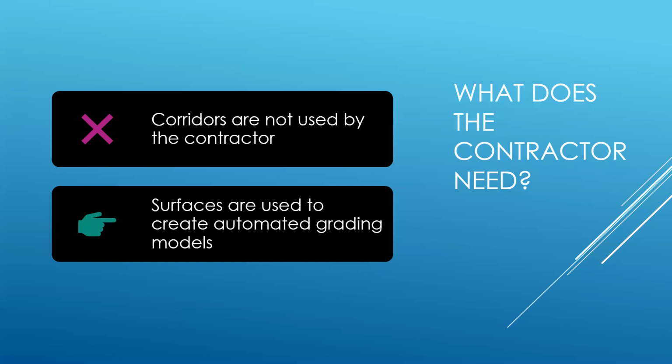So once we completed the Highway 15 project, we wanted to reflect on what we had done. We wanted to question why we use stage models, and we wanted to determine if there was a better way. So first, we questioned the need of stage models due to the issue we found with the lack of flexibility to change. Essentially, we found the only benefit to using stage models was the ease of creating stage surfaces and modeling the interim drainage. So we took a step back and we said, is there a more efficient way? Could we avoid splitting up our models, but still be able to create stage surfaces? And a bigger question is, do we need stage models at all?